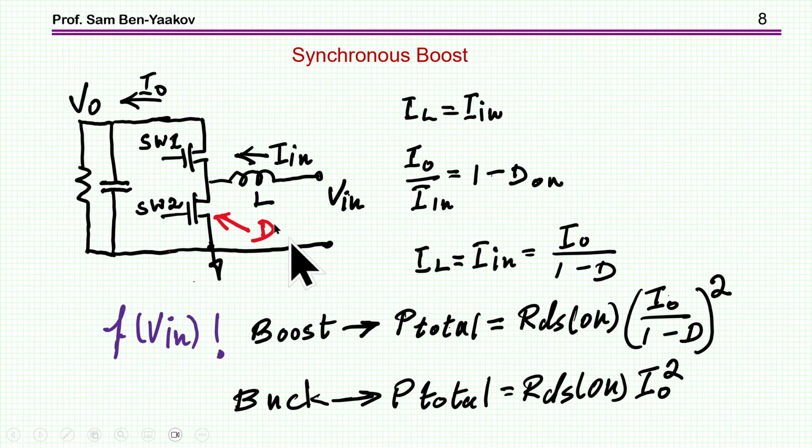Now, what about the synchronous boost? Here we have an entirely different story. Well, first of all, the input, of course, is coming from here. The output is coming from here. Notice that the structure, the topology you might say, is exactly the same, except that the input now is from here, while in the buck it's the output port, and the output is here, while in the buck it's the input port.